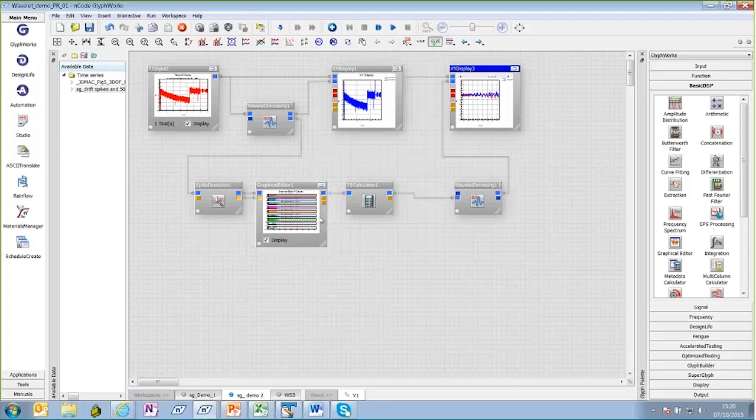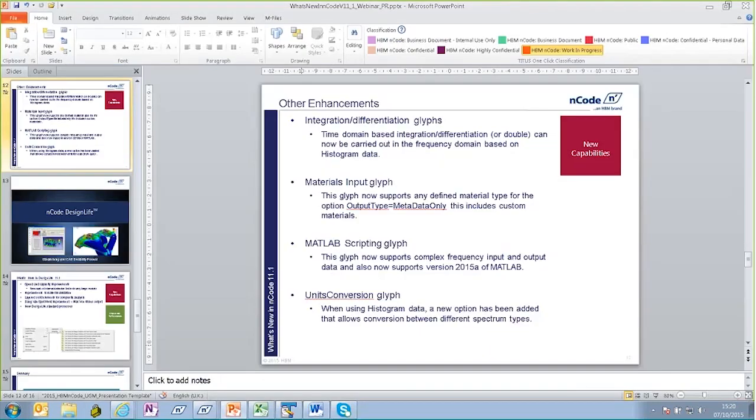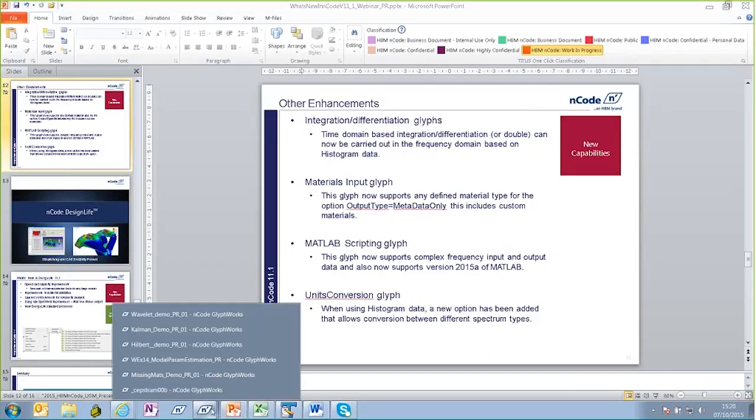It's probably not applicable to most normal spike detection and normal filtering that would be applicable to most data. So if you've got normal data where you know the frequency content and you can take that out with a filter, that's still more appropriate to do. And it's still appropriate to take out most spikes within the time domain. But this gives you some extra functionality in data where you couldn't remove the noise problems in that way. So that's a wavelet example.